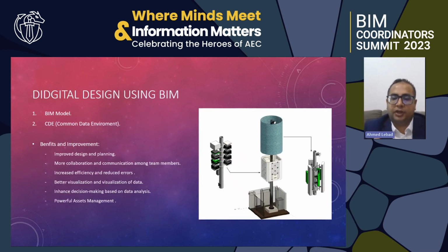As we collect this more enhanced digital survey data, for sure we should apply a technique to get benefit of this, which in our case is BIM. As all of us know, BIM gives us improved design and planning. Instead of a 2D drawing, you will have a 3D view. So it's better visualization, which increases decision making and makes it easy to decide where to put our antenna and the accurate azimuth of the antenna, and you could detect any clashes with existing antenna or even mounts.